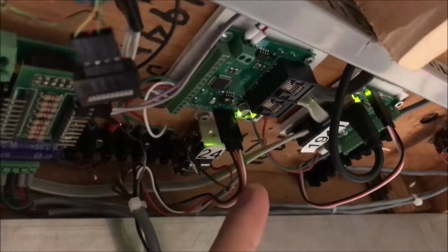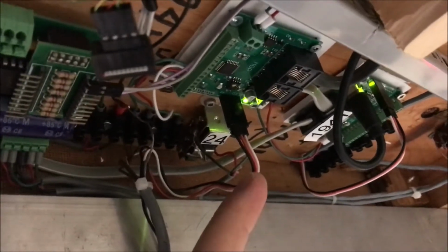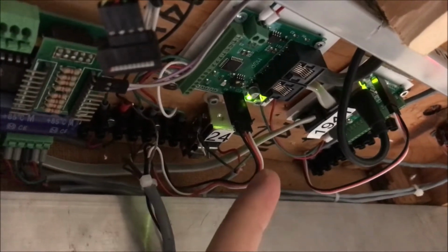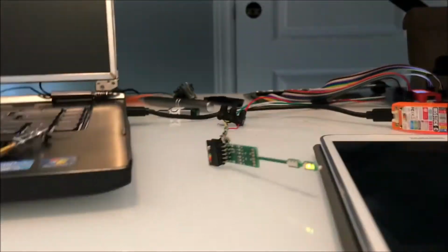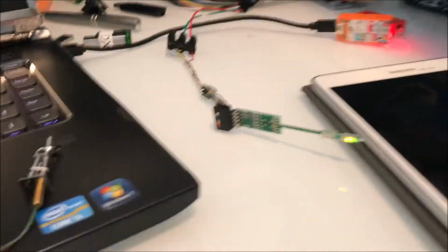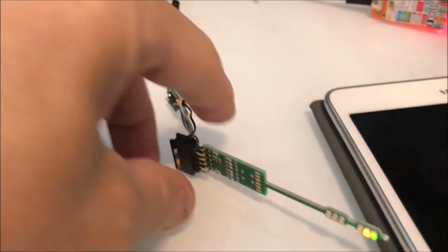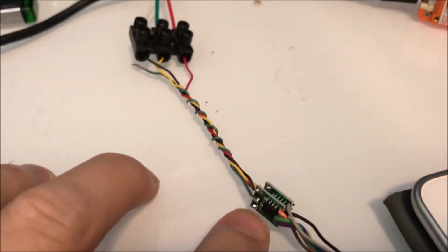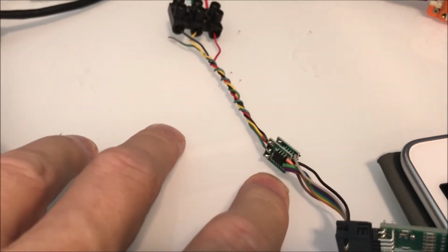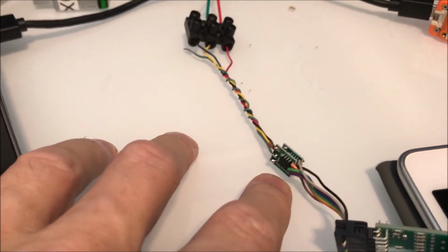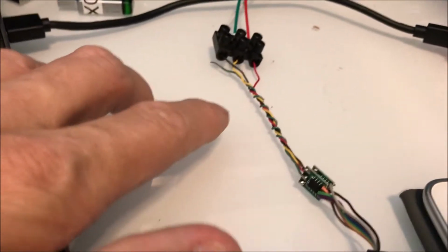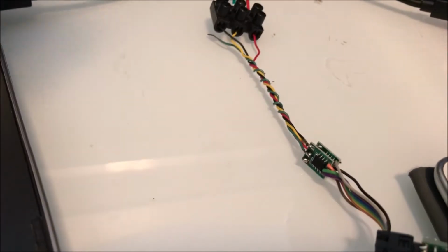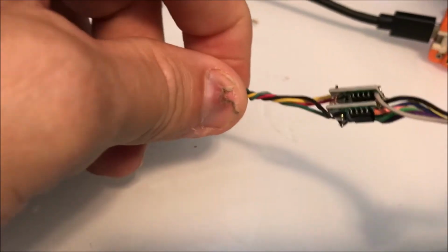In this case, you have this bus wire here, which is a servo type connection, and it gives out 5 volts, ground, and then a signal. To modify those signal heads, since you see it started off as something like that, I ended up putting these little boards here, which are WS2811 chips. They convert the LEDs, so they run with those boards. So basically, you have 3 wires coming in, and in this case I have 2 of these tiny little boards, 1 for each head,